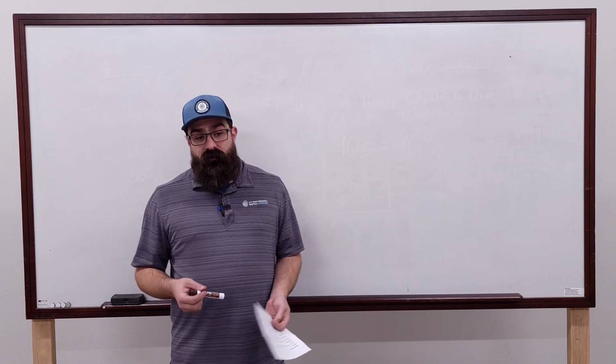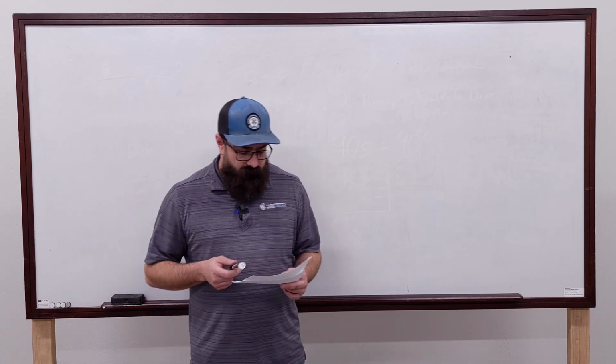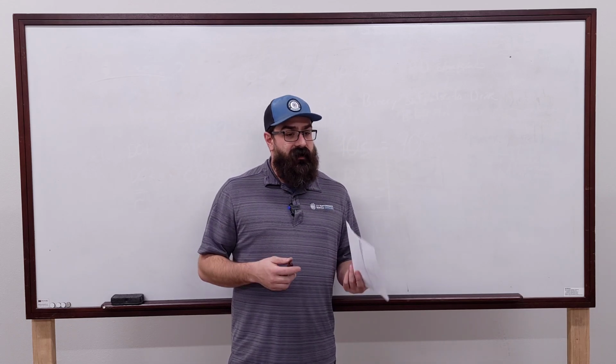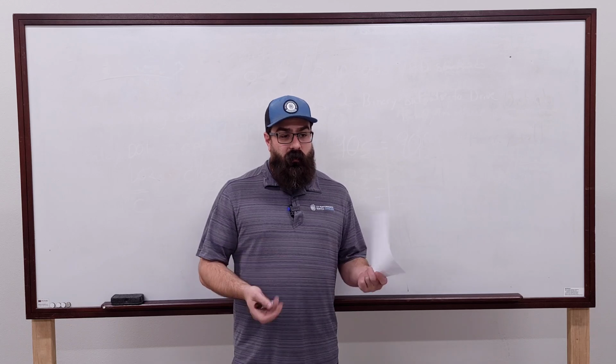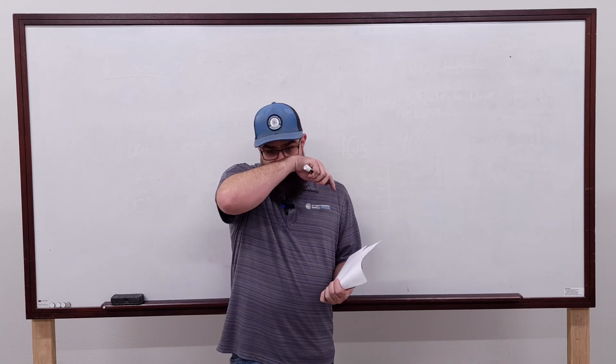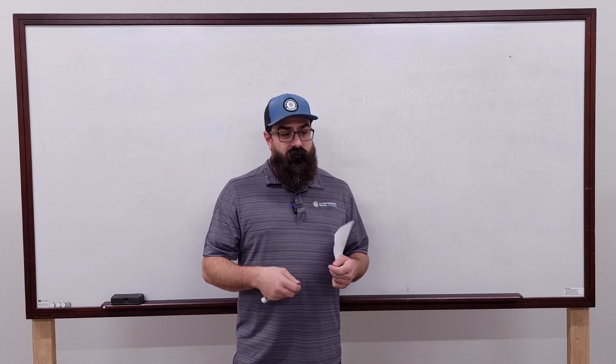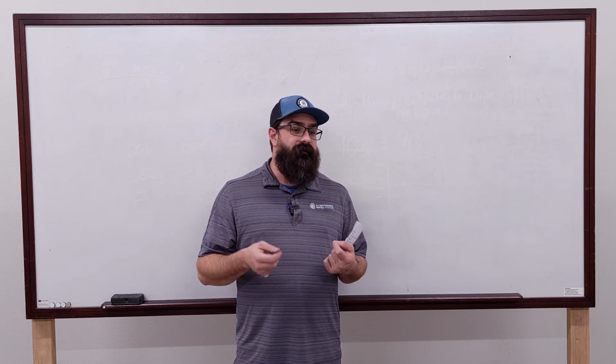As far as checking outputs, oh, hang on, we'll get to, yeah, we'll do outputs. Kind of went over it with the Triacs, putting a meter on them. You're always going to show voltage if they don't have a load. If you have a load, like a little relay hooked up to them, then you'll be able to really tell if they're calling or not.